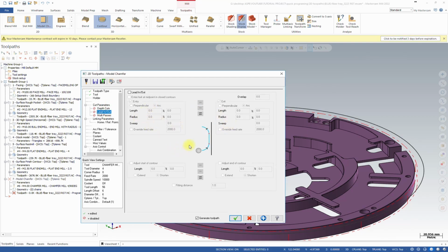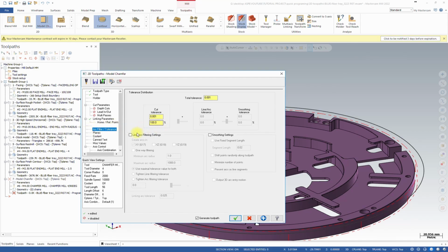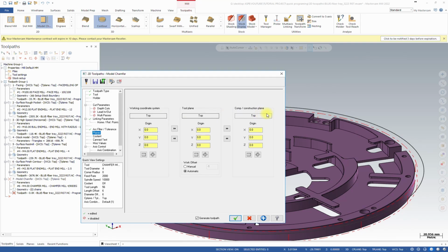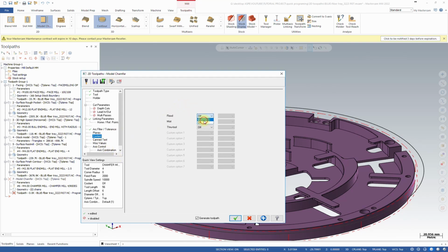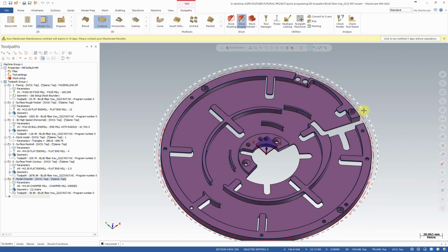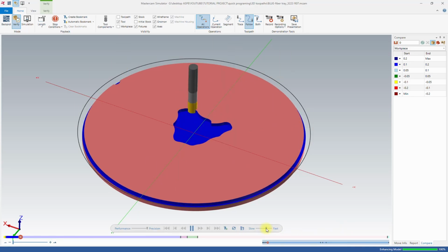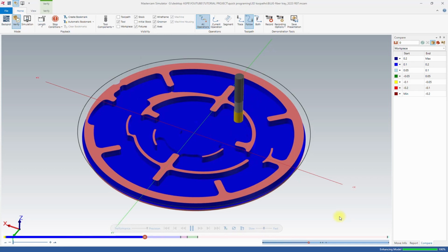No depth cuts. I'm not going to use any lead in and lead out. Multiaxis, no. Linking, I can go back to 5mm clearance. Feed plane, 2mm. Most of the features are on the top edge anyway. Arc filter, we're going to do filter in 85% to 15 cut tolerance. Planes, top, coolant on. And we have all the settings ready. And this is our toolpath. If you want, you can add, of course, lead in, lead out, but for chamfer, I do not need that. Let's quickly jump to verify simulation, and we can see our part being machined.